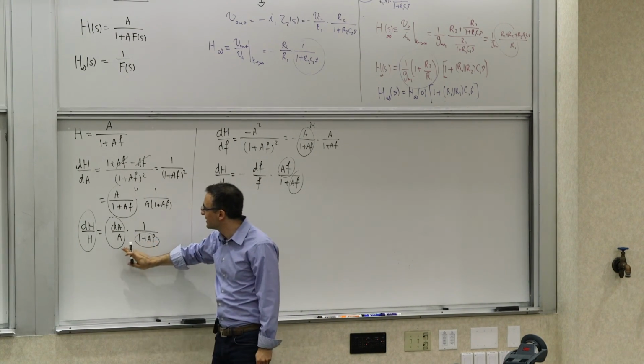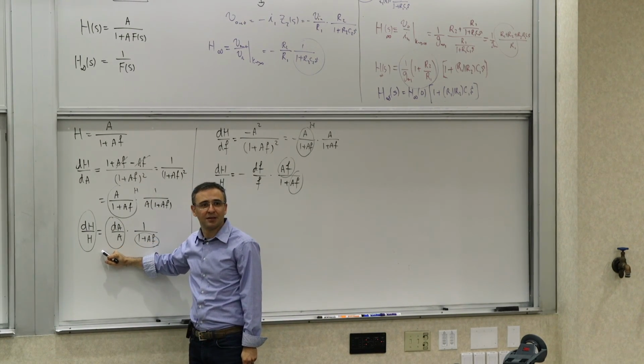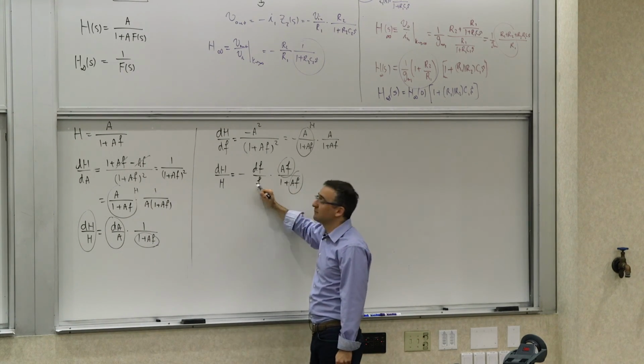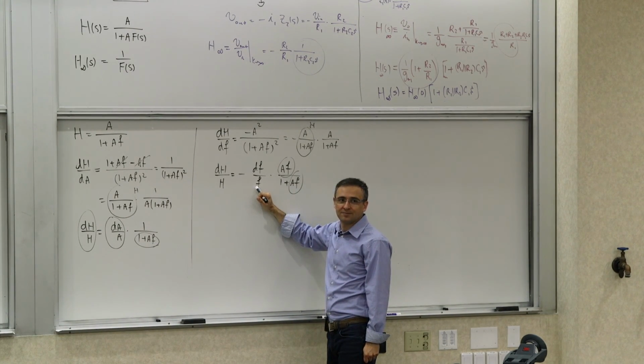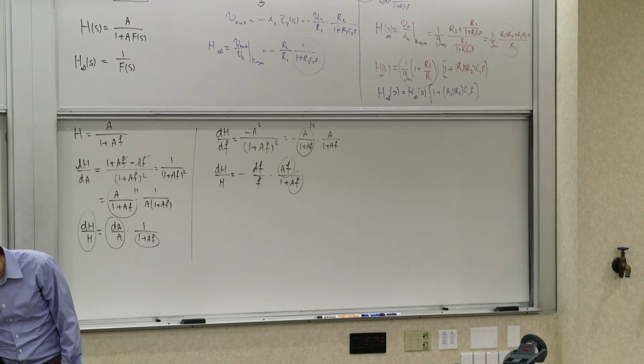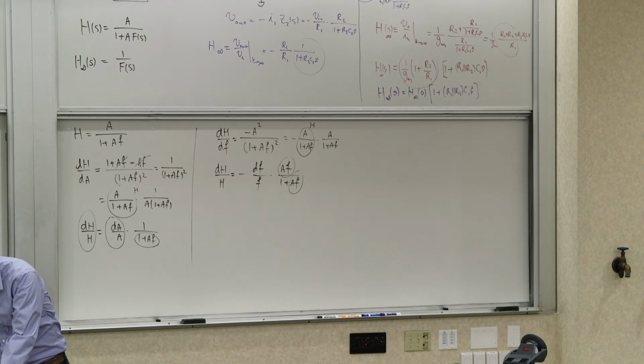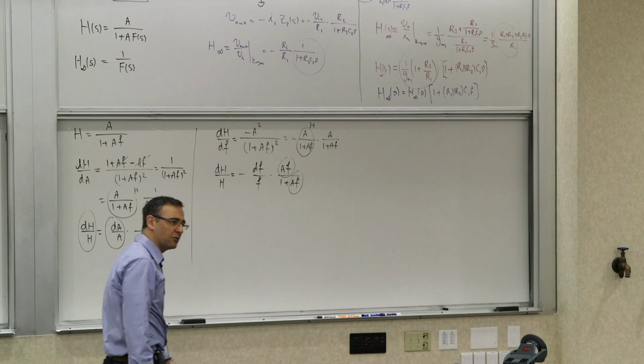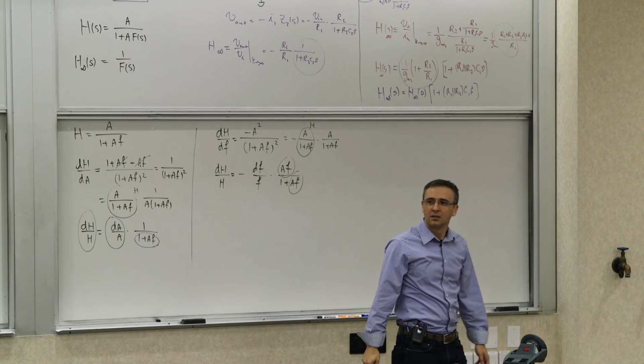There is desensitization to the forward path, but there is none for the feedback path. That's an important thing because it allows you to design in a way that is conducive to repeatability and reliability. Okay, any questions on that? All right.